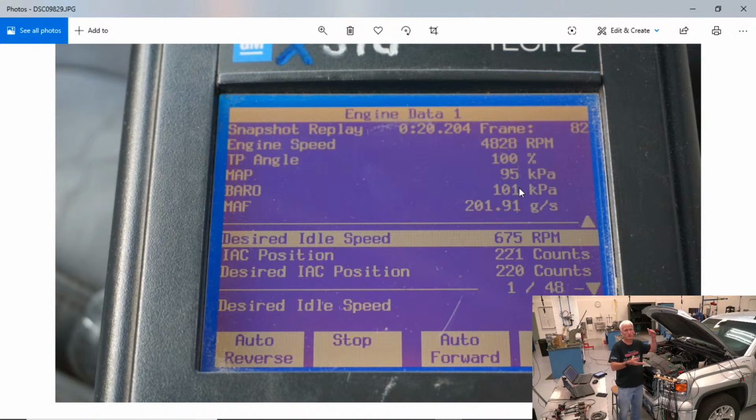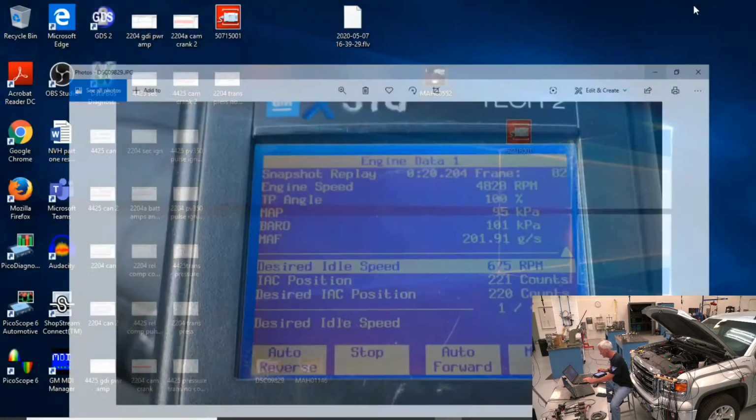And then the fuel trim numbers go up. Same thing if it's over-reporting the amount of air. If it thinks there's way more air coming in, it mixes a lot of fuel with it, even though there's not that much air coming in, then they have to trim that fuel out because it was too rich. So, long and short, that was kind of a long way to explain. But I do have an issue, so that'll be something I can look at. I didn't really think there was anything wrong with the truck, but I think there is, looking at those numbers.